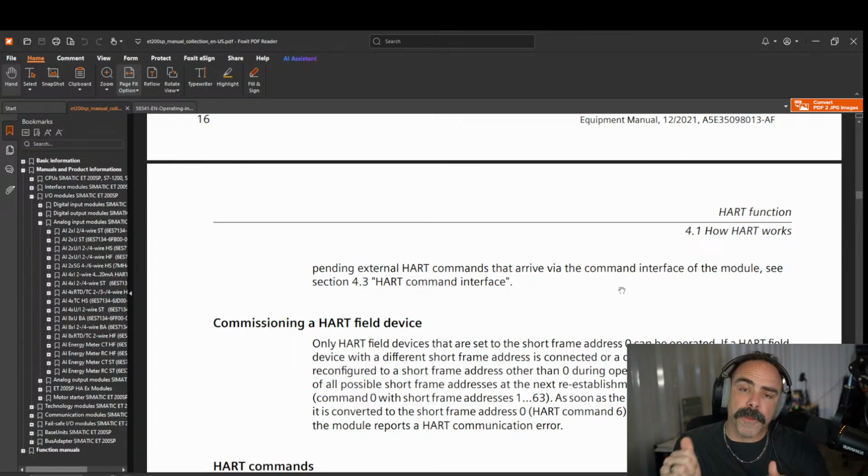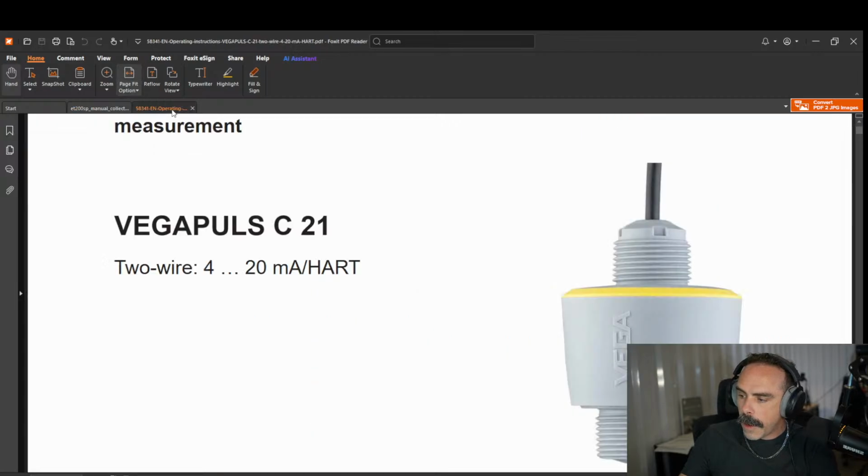And on the device side, so the actual level sensor or whatever, that is kind of varied. And so what you have to do is bring up your device manual, to say, okay, what by default are these variables? So your primary, secondary, third, and quad. So primary, secondary, tertiary, and quadra, whatever. It's some weird quad thing. So you get that information from your device.